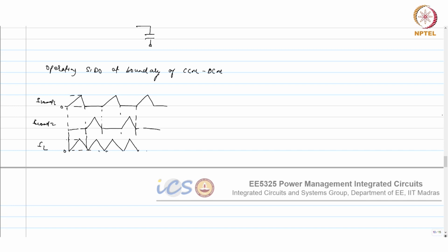So there is no time during which you have a high Z region. So the inductor is not resting. As soon as the inductor reaches 0, you trigger the other phase. But the problem with this is that the frequency will vary when the load current changes. When the input or output is changing, your slope will change, so it may reach the 0 point at a different time. Or if your load current is changing, the same may also happen.